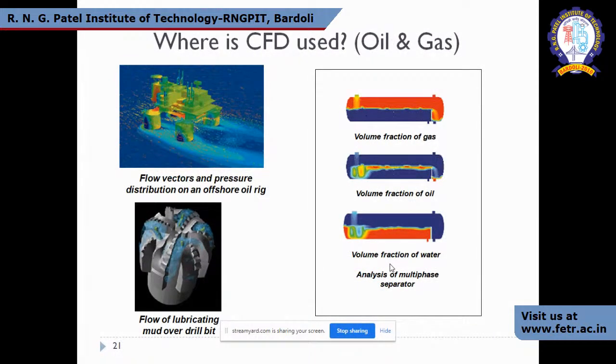As far as oil and gas is concerned, we see a number of tanks that carry partially filled gas or oil or a mixture of both. When the truck moves, there is an interaction between this gas and oil, usually known as sloshing of the liquids. Sometimes this motion may cause failure of that particular vessel. Hence, we can simulate how the fluid moves when certain motions are applied.